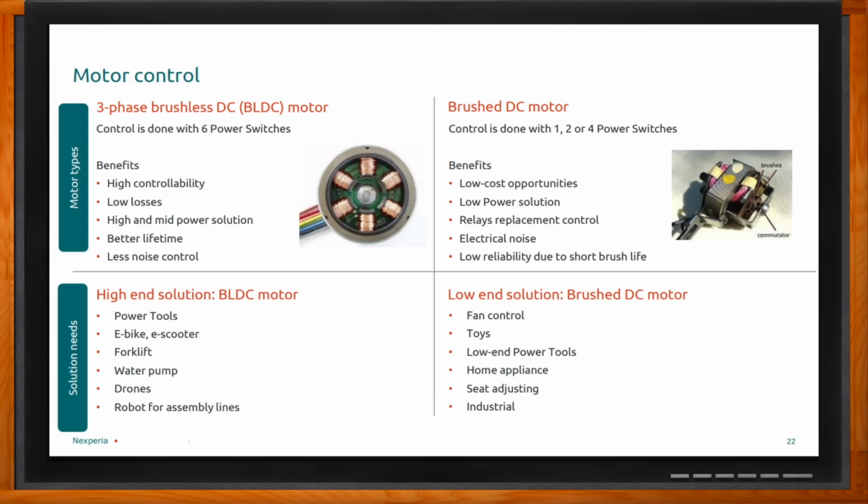And they used to do servo amplifiers, were good at that, and now it's a lot less expensive with a digital approach. A good example is the brushed DC motors, which were used extensively in automobiles, in fuel pumps. So if you can imagine a brushed motor with the brushes arcing inside the fuel pump where the fuel is combustible, it's gasoline. And so most manufacturers have moved away from that and went into brushless motors.